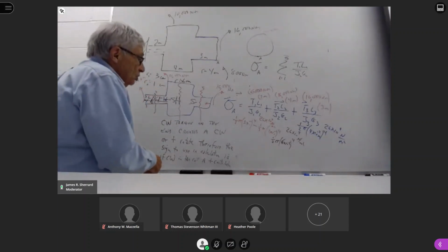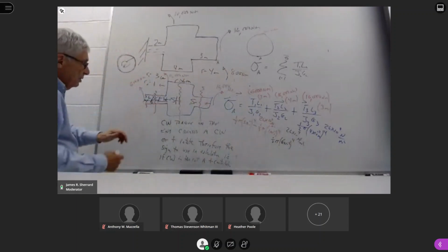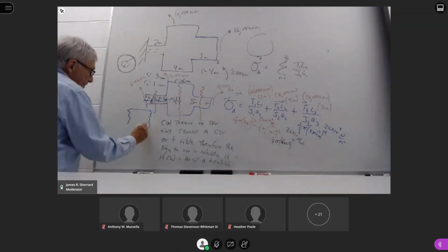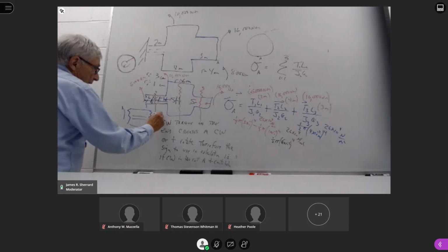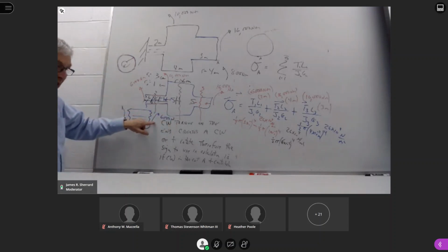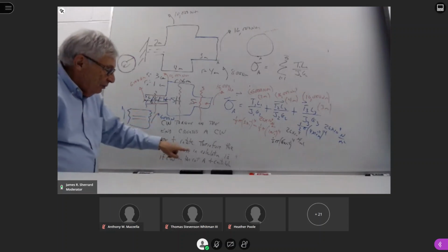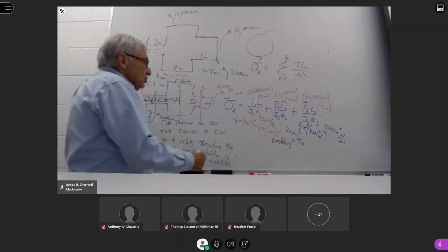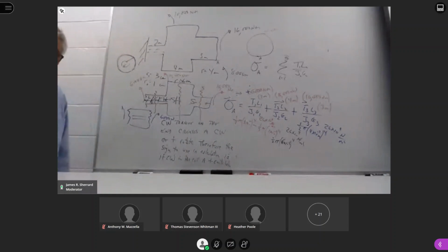So if you go back through and you look at each of the sections, when we did the free body diagram for this first one, we had this was equal to 6,000 Newton meters. Which way is it going? It's going clockwise. And we said if we have clockwise in the cut, it's a positive contribution. So this value is positive.